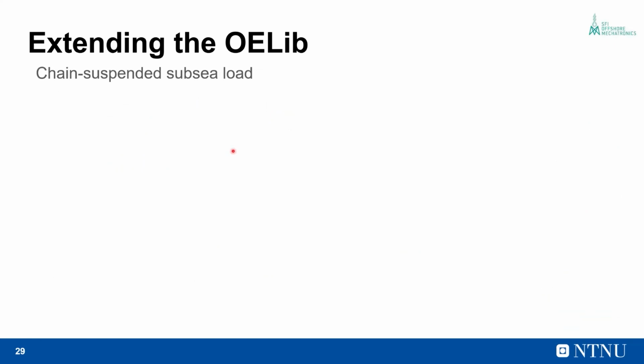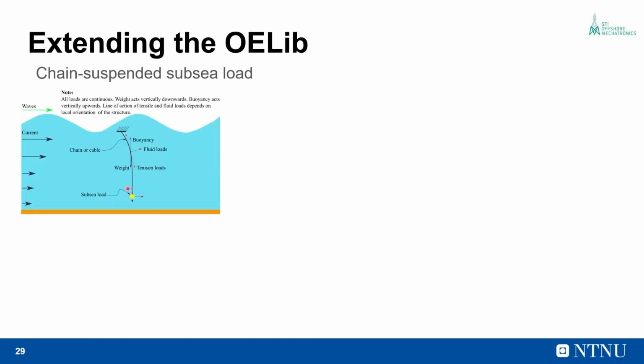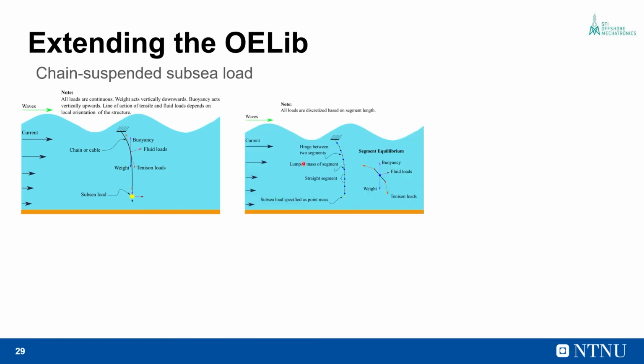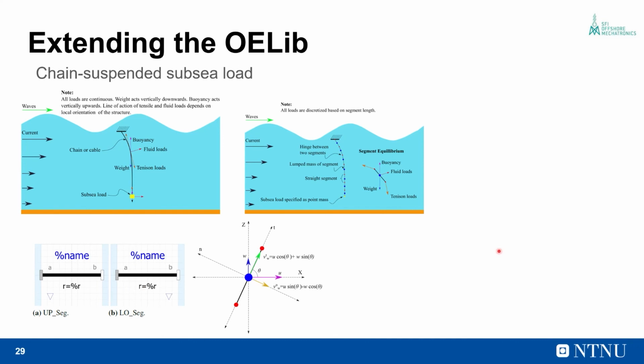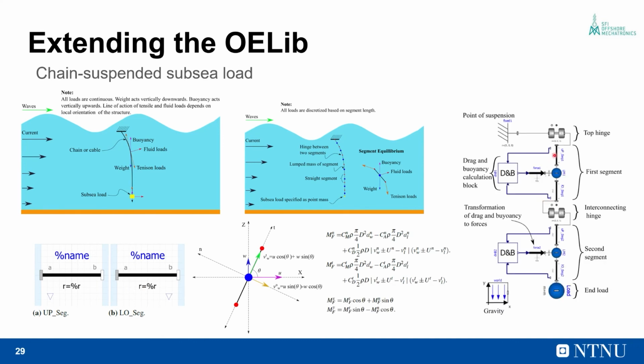And in another publication, we present the results for the dynamic simulation of a chain suspended subsea load, where again we use the lumped mass approach. But in this case, we modify the components already available in the standard Modelica library to build up the model of the chain suspended subsea load.